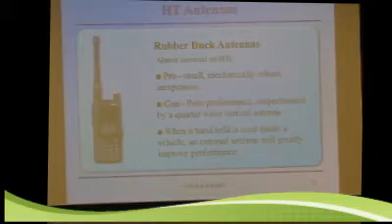I didn't bring in my radio this week, but if you saw last week, I had about a quarter wave antenna. I did not have the stock antenna that came with it. About a quarter wave antenna will do substantially better for the same power. And so almost every handheld radio I get, I buy an additional quarter wave antenna because it's only about 19 inches, and even on my hip, 19 inches only goes a little ways up my back. So I'd rather have the inconvenience of a quarter wave and get the performance advantages than have a little bit shorter rubber duck. But lots and lots of people use them with repeaters. They work pretty well because you don't have to have a great antenna.